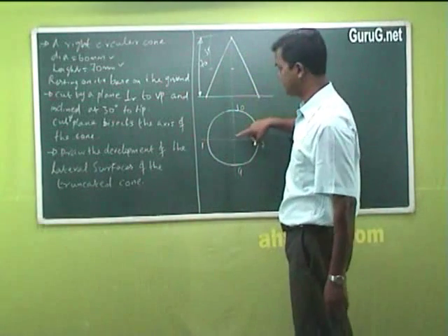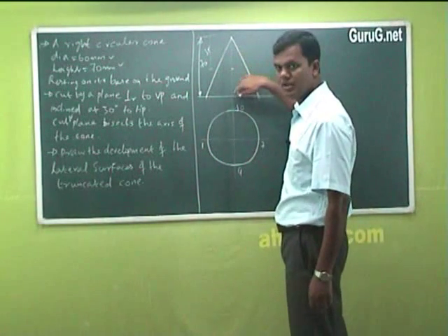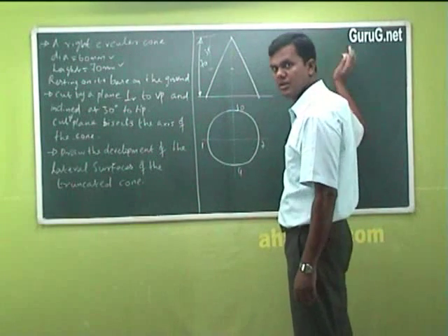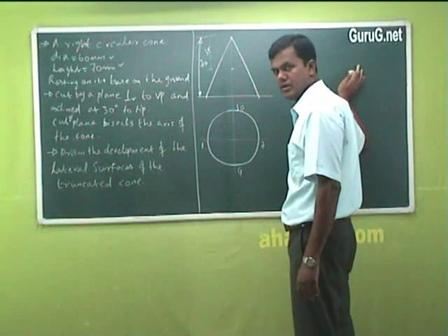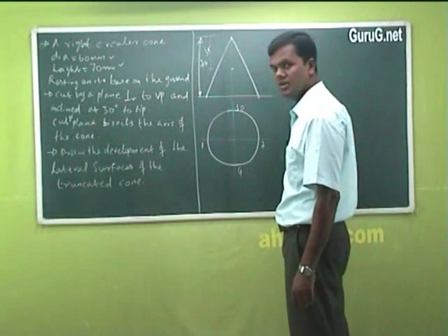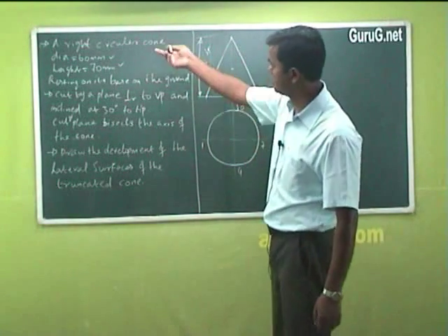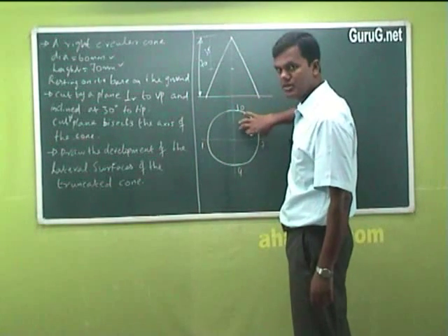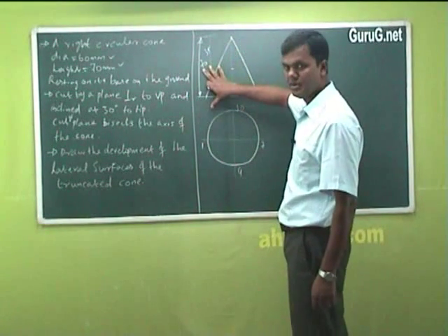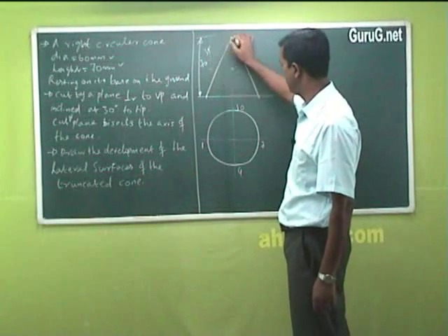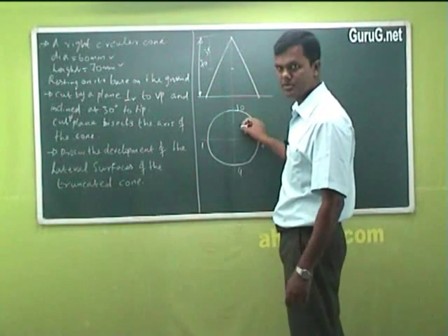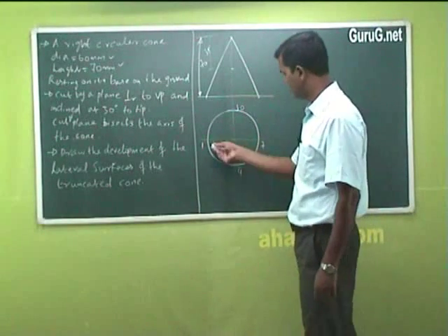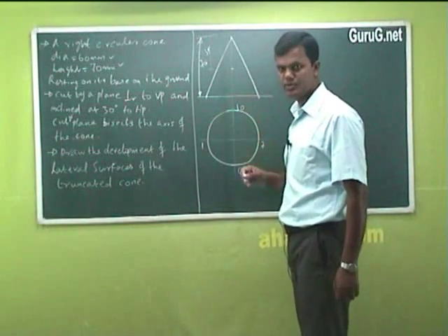Now the next step is to draw the cutting plane. So the truncated portion you can show in the developed surface, the development of the particular right circular cone. Now what you do, after drawing this circle, you show the axis 70 millimeter, and the remaining marks you can give as P, Q, R, S, T, all this. I have divided it into 12 equal points, so 1, 4, 7, 10, and you will end up with 12.